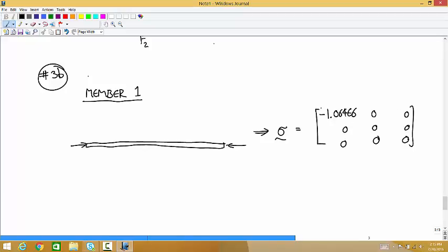So once you're here, to calculate the maximum shear stress, you need to get a principal stress tensor and then rotate the coordinate system 45 degrees around the middle axis. This one you can skip the step of getting the principal stress tensor because this is already one. There's no shear stresses.